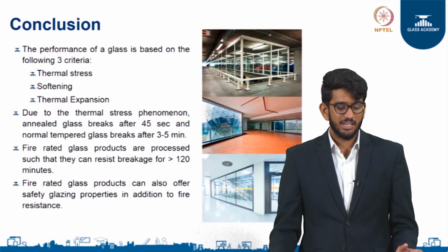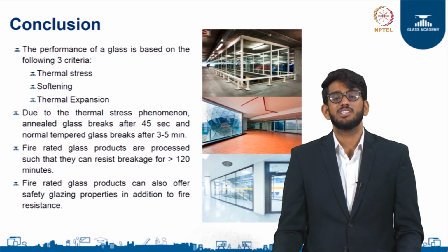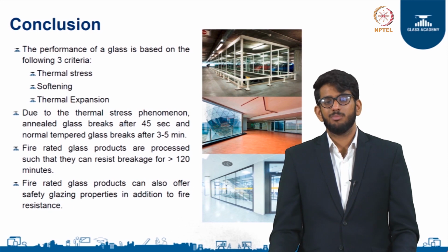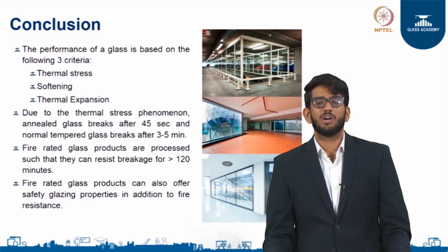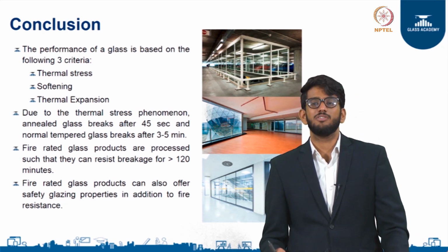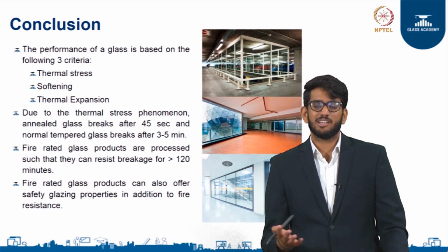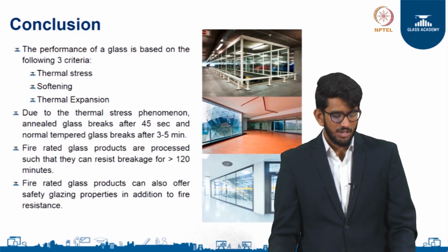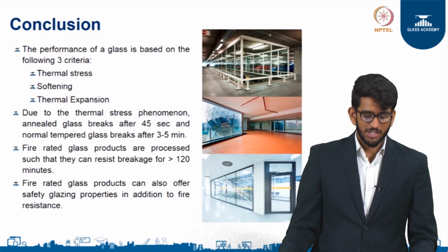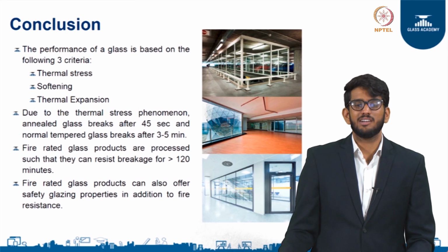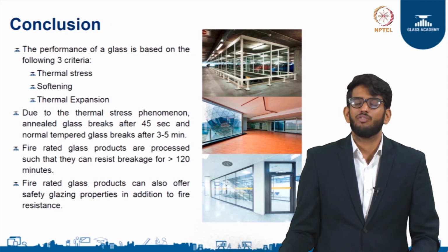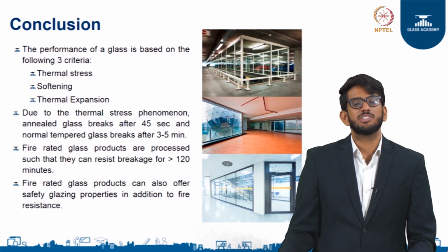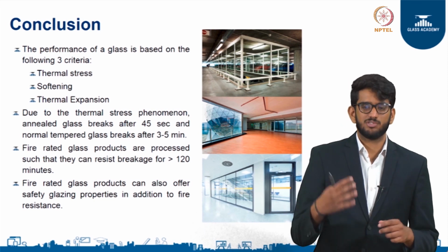And the third criterion on which the performance of a glass can be judged is definitely thermal expansion, because we are talking about close to 1200 degrees. So, there is bound to be a lot of expansion in the systems, let's say in the glass or the frame which holds the glass itself. Due to the thermal stress phenomenon, a normal annealed glass will break at 45 seconds to 1 minute is what we saw. A tempered glass will break within 3 to 5 minutes, if you remember the graph that I showed you.